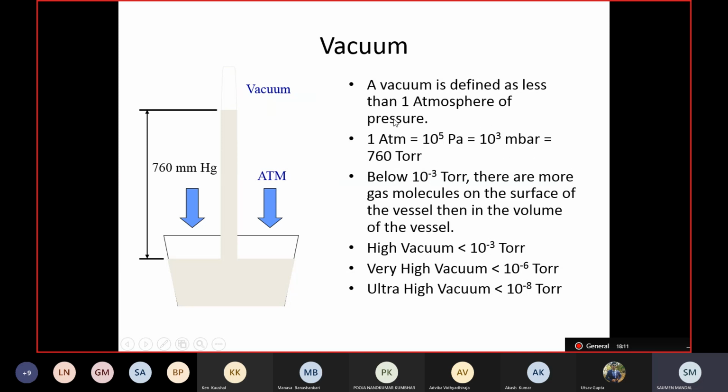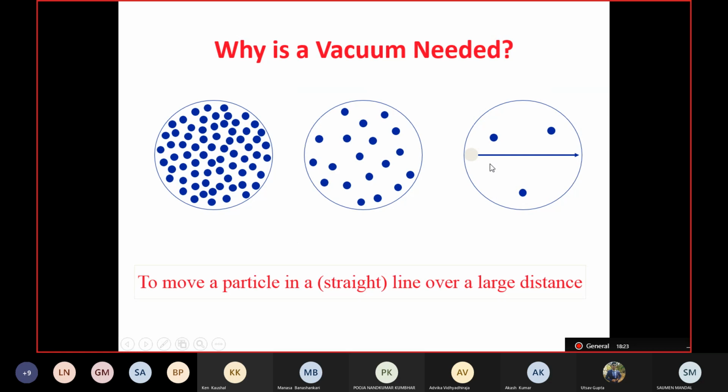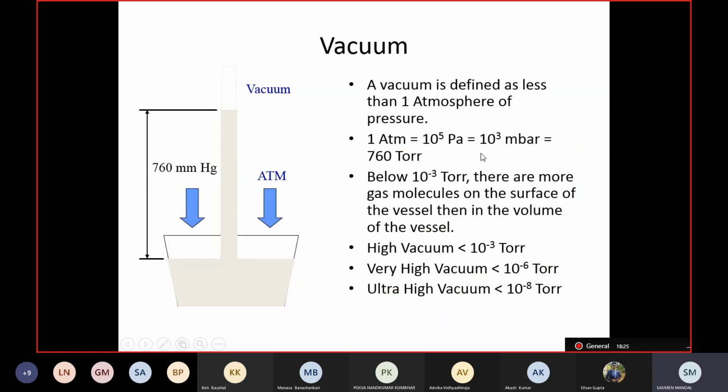These things you have to remember. Then there is absolutely no problem in any chamber; you can understand the vacuum level compared to atmosphere. In India, most instruments use atmosphere, Pascal, millibar, or torr. Atmosphere is rarely used; mostly Pascal, millibar, and torr.